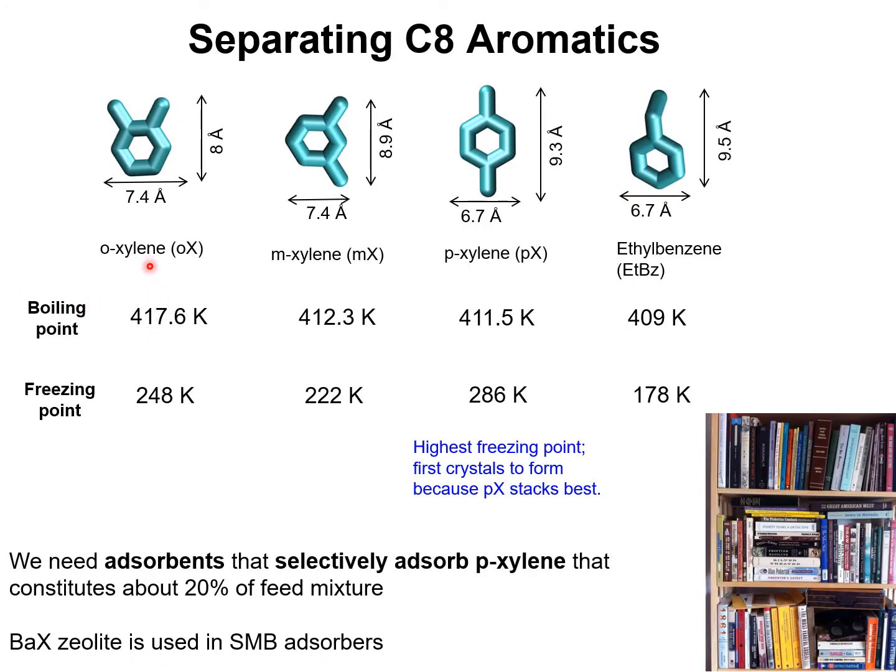Let us examine the separation of C8 aromatics. The boiling points of the four C8 aromatics, ortho-xylene, meta-xylene, para-xylene, and ethylbenzene, are very close to one another, and distillation separations are not feasible.